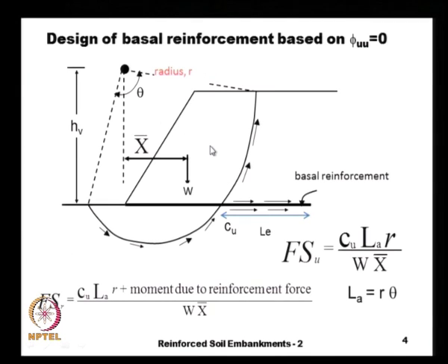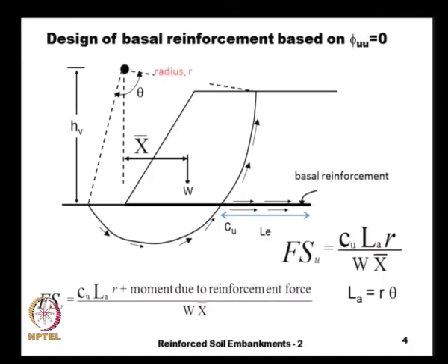Just to recall, in the previous lecture we have seen the design of soil slopes with the basal reinforcement layer, and the basal reinforcement is provided for several reasons. Especially in the case of extremely soft clays, we require a working platform so that we can even bring in our construction machinery and start mobilizing our equipment. And then of course, on top of that we may require some extra reinforcement to improve the factor of safety.